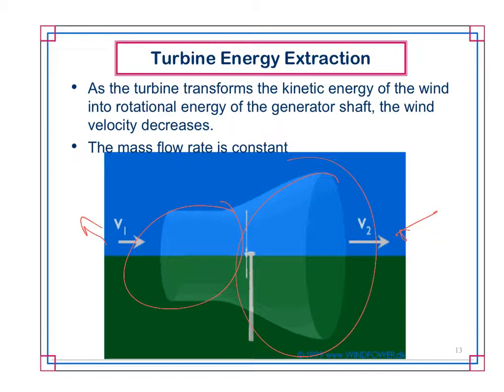over a greater area because you've got a certain amount of particles at a slower speed, so it basically has a different density there. So what we're also assuming is that the upstream and downstream velocities are going to have a constant mass flow rate. So the amount of air moving, okay, not the speeds, but the amount of air that's being moved, is the same. And that hopefully helps you understand why that's such a bigger area, because it's at a slower speed, but you still need to have the same amount of mass. You need more room to do that.